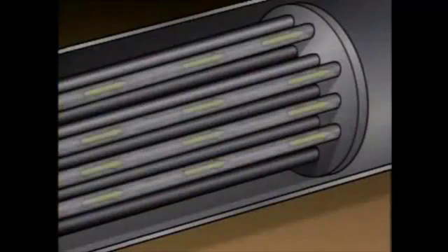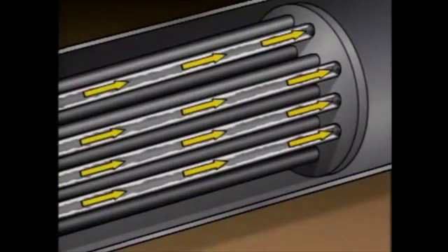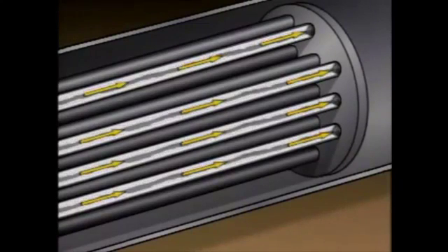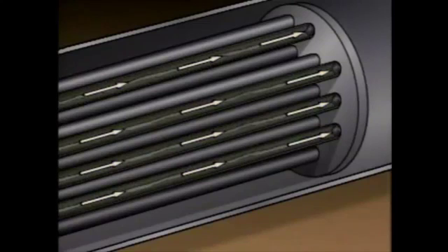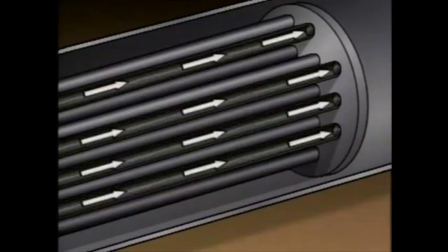One common cause is impurities in the fluids passing through the heat exchanger. For example, in a process that uses water, impurities such as calcium can come out of the water and form an additional layer of material. Another source of fouling is small plants and animals that enter the heat exchanger. Many forms of algae and bacteria can live and grow inside the unit and form a layer of slime on the internal surfaces of the heat exchanger.